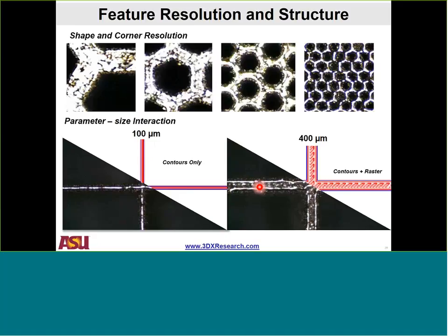And if you remember back to my equation where the modulus scales by the thickness over the length, it also goes by the mechanical properties. On a bulk structure where you have a lot of rastering and the contours only apply at the skin, that may not be an issue. When you get down to these finer and finer scales, the relative relationship between rasters and contours, at least for scanning or extrusion-based additive processes, could be relevant. So there is that to think about when you get down to really fine structures. A is how well you are resolving your geometry, and B is the interaction of your process as a function of variation in that geometry.